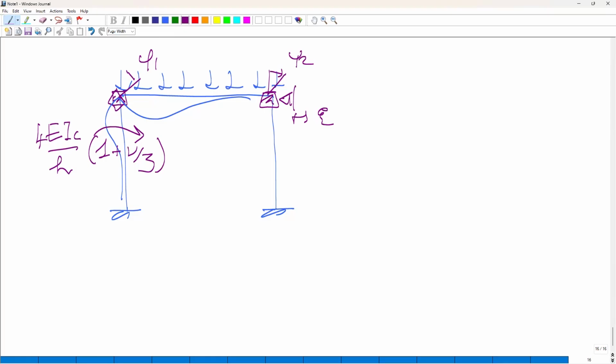But what is inside this Ni? Well, Ni is the value of the axial load applied on that column divided by the critical load. The critical load, if you have all the geometry properties, you can compute. But do you know the axial load on the column? If you don't solve the structure, you don't know the stresses inside them. So actually, the buckling or second order analysis of a frame structure is an iterative process. It's not a one-step process, where you perform the structural analysis, first step, and you get the result. It's an iterative process.